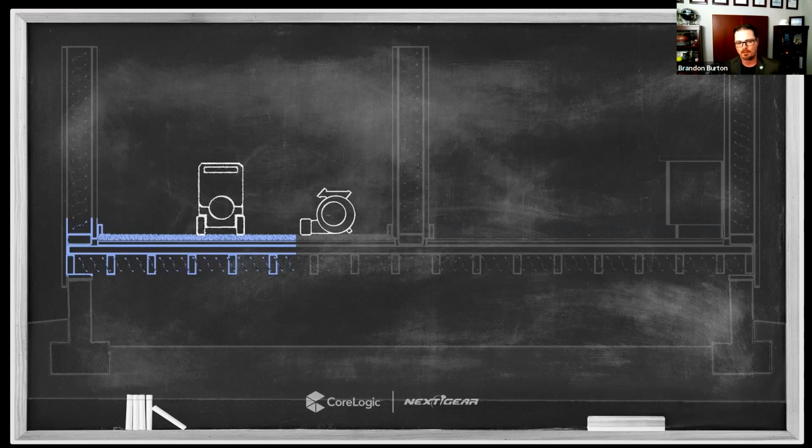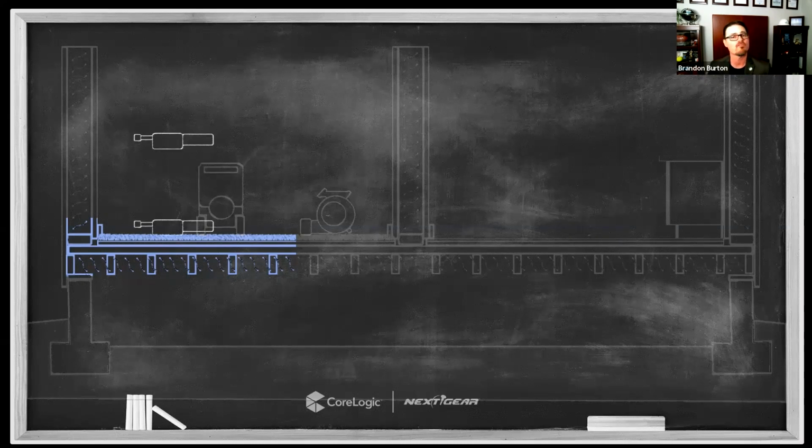Now, in the previous episodes, you've probably heard me stress just how important that interaction at the surface is. And the key with air movement is exactly that. To validate whether or not air movement has been effectively deployed, the best way to do that is to use a thermal hygrometer. And we talked about some of these measurement principles in earlier episodes.